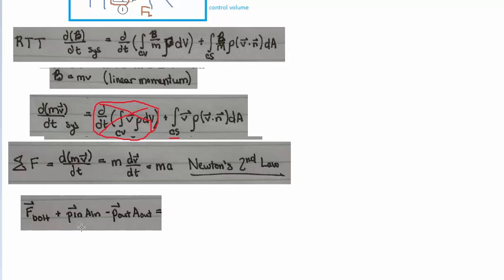When we're working with pressures, we need to use that area, because remember, pressure is force divided by area. So force is pressure times area. Whenever you're working with pressures, don't just start adding forces and pressures. That's a common mistake. Make sure to always have the areas along with your pressures, because that'll get you newtons, newtons, and newtons.